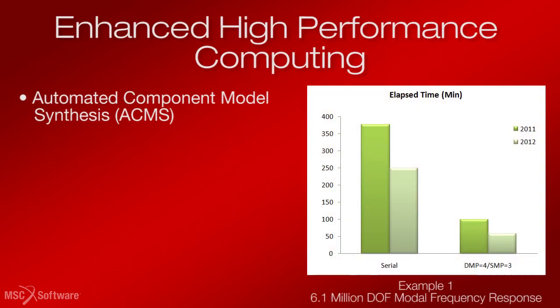Automated Component Modal Synthesis, or ACMS, is enhanced to better utilize all available processing power on a multiprocessor system or on a cluster of multiprocessor systems, enabling users to improve the solution efficiency of large modal frequency response analyses.